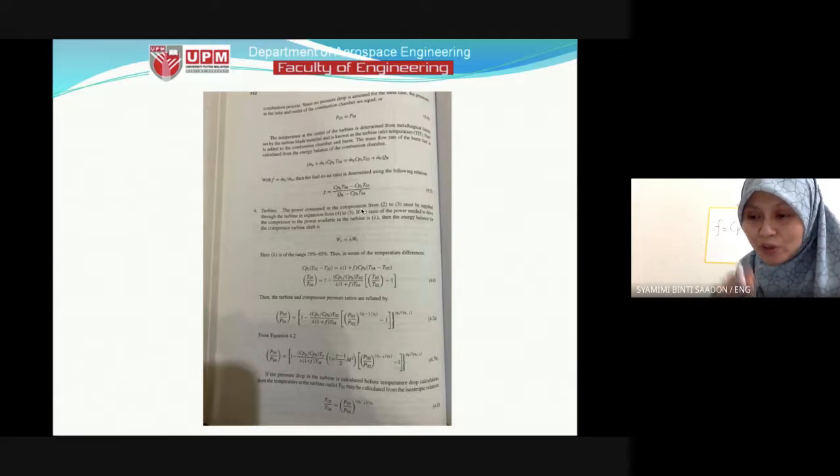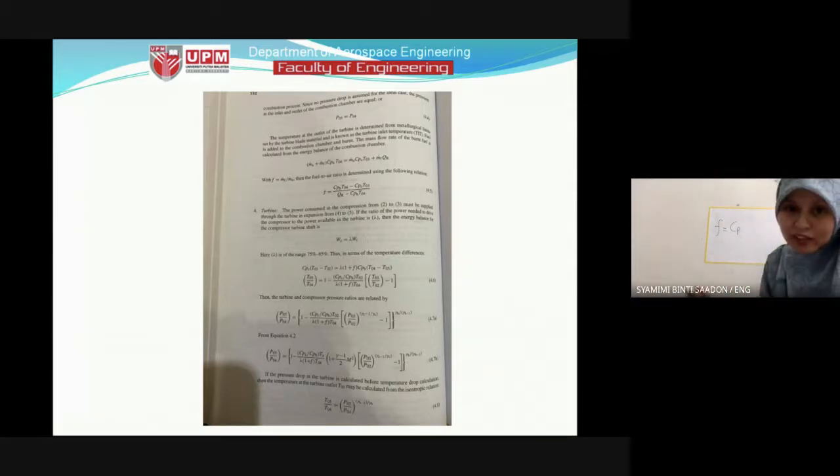So if we go into more detail, sometimes the specific heat of the fluid after exiting the combustion chamber is slightly different than before, because we have mixed with fuel. But here we assume that the Cp, specific heat, before and after the combustion chamber is the same. So I just write it as Cp.